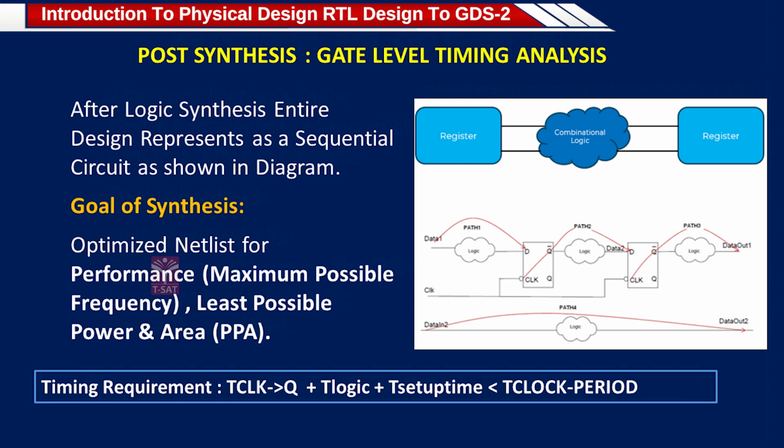Generally, you have different sequential cells, right? JK flip-flop, D flip-flop like that. In general, people use D flip-flops in ASIC design. So, that is the D pin of the flop. Started with your I/O pad and going to the D pin of the flop. And next one, path 2. Start with a sequential cell and end with the next sequential cell.